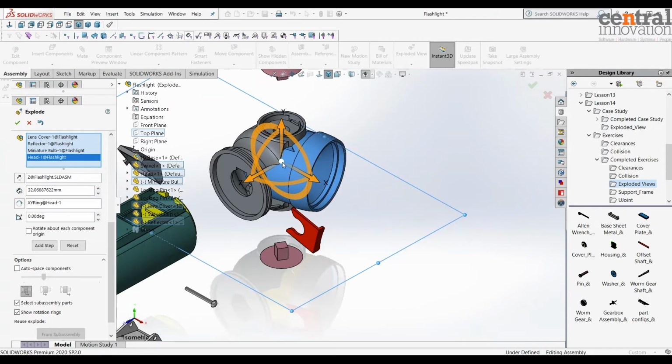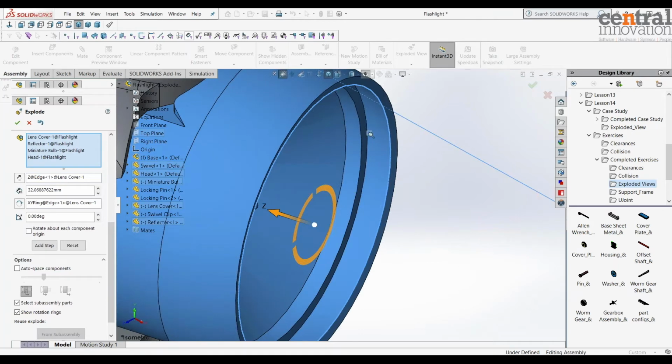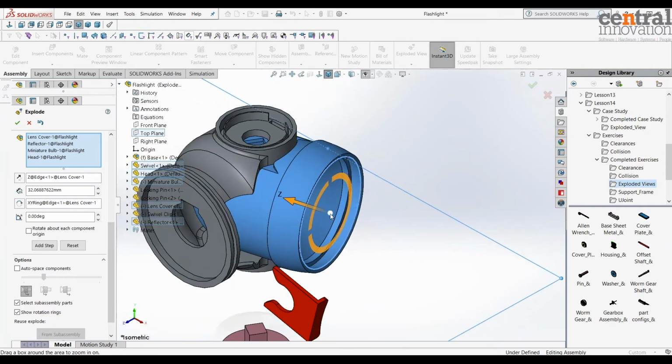So simply I just drag this white origin here and drop it to this edge. And as you can see now, I have this direction exactly perpendicular to that surface. Let me zoom in and you will see which surface I exactly mean. This surface, okay? So I just drag and drop the origin of the triad to one of these edges.